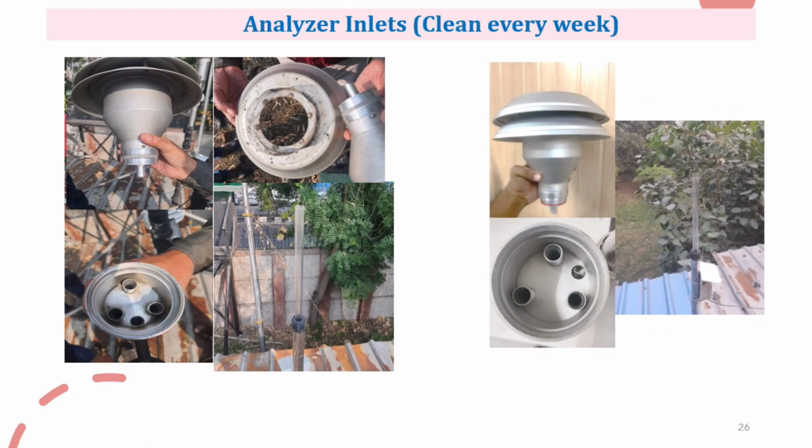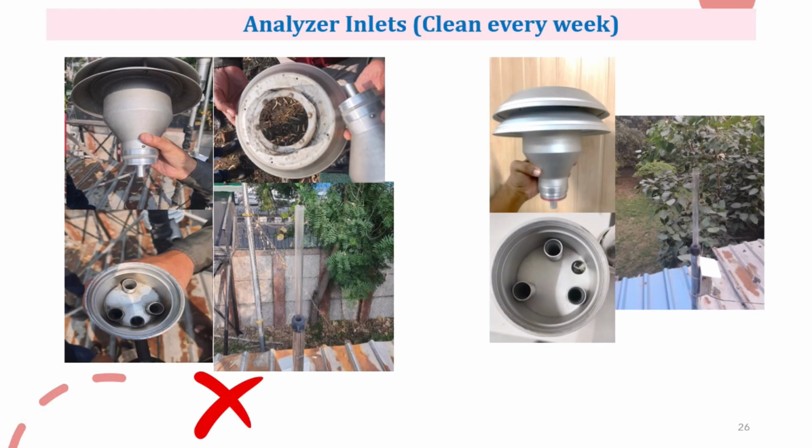It's crucial to keep the analyzer inlets clean and properly greased. This ensures they work smoothly and helps to prevent any blockages or damage. This maintenance is vital for getting accurate measurements.